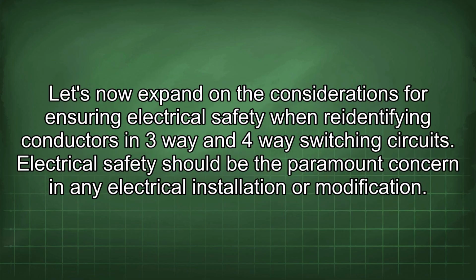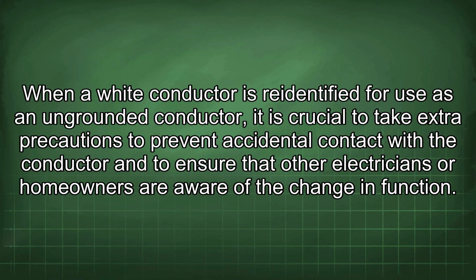Let's now expand on the considerations for ensuring electrical safety when re-identifying conductors in three-way and four-way switching circuits. Electrical safety should be the paramount concern in any electrical installation or modification. When a white conductor is re-identified for use as an ungrounded conductor, it is crucial to take extra precautions to prevent accidental contact with the conductor and to ensure that other electricians or homeowners are aware of the change in function.